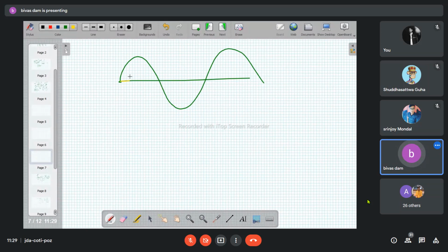Now if I fire the SCR at this time instant, that means prior to this gate pulse, there was no conduction of current in the circuit. So the output was something like this. I am drawing only this half. So the average power content of this part is definitely much less as compared to this part. So the speed will be lower.